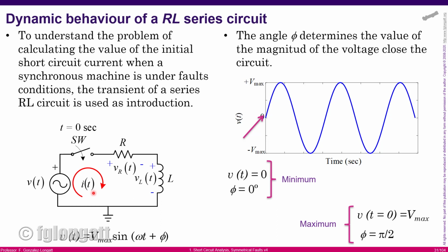However, probably you are wondering, okay, this is basic circuit analysis. Why do I need to learn this, okay? If you remember from your classes of electrical machines, the most basic model for a synchronous machine, without going into so many details about saturations and so on, what I need you to remember is that we can create a model that is an impedance behind a voltage source. An impedance behind a voltage source.